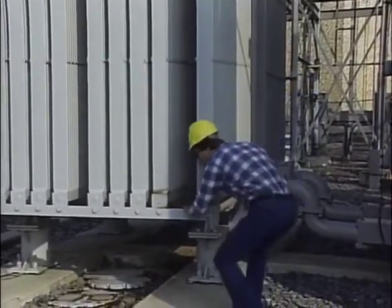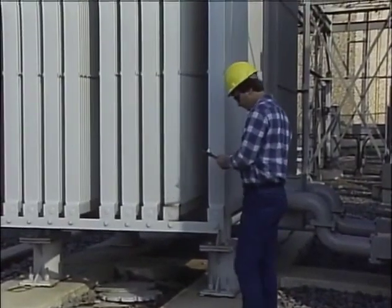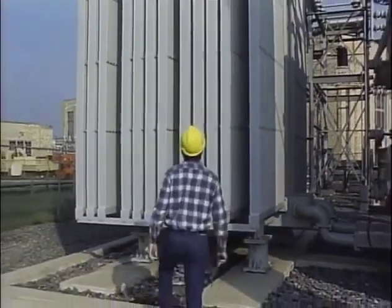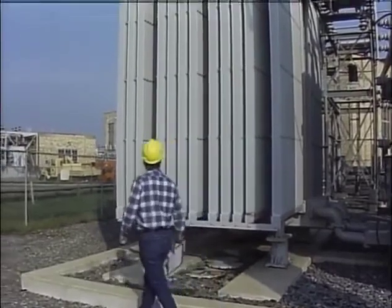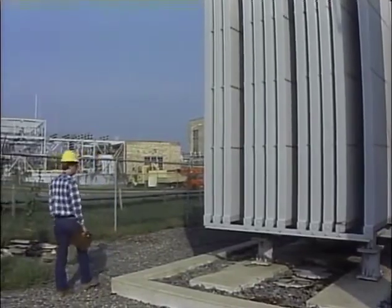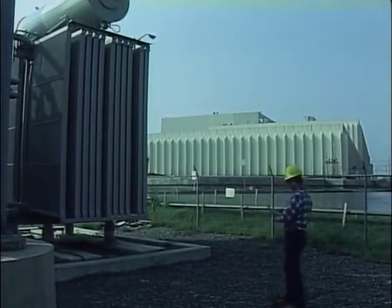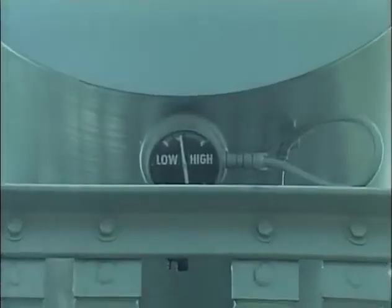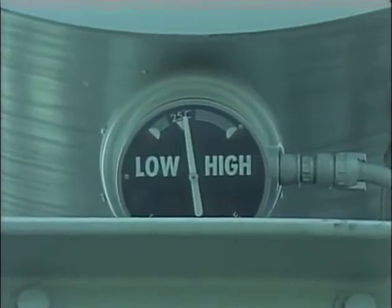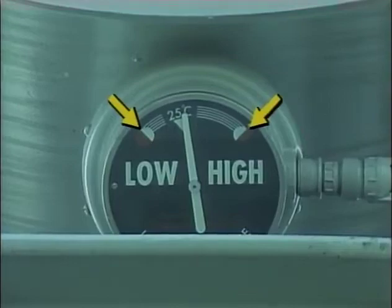Any device that contains oil may develop leaks. Some common places where leaks occur include welded or bolted seams and around valves. Any leak or sign of a leak should be noted so it can be monitored or scheduled for maintenance. If enough oil leaks out of a reactor, the reactor could be left without adequate insulation and could fail. For this reason, an inspection of an oil-insulated reactor should include checking the oil level. The oil level will vary some with changes in outside temperature and with changes in the load. In general, if the level falls outside of this band, the cause should be investigated and corrected.